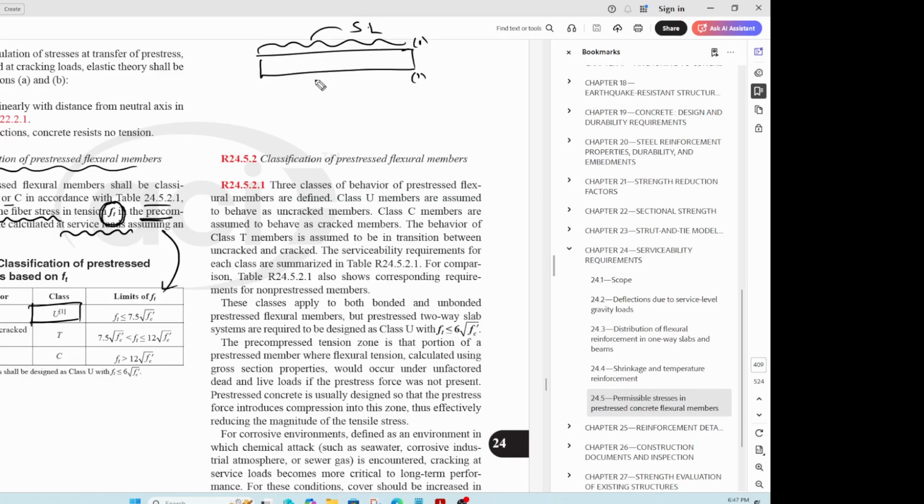So you'll have to find the extreme fiber tensile stress, and then compare that stress with the rupture modulus of concrete, or the tensile strength of unreinforced concrete. And that's why you will see this term being compared with a term called 0.75 root f'c, and this is the tensile strength of concrete with no reinforcement in it, right? Or modulus of rupture of concrete.